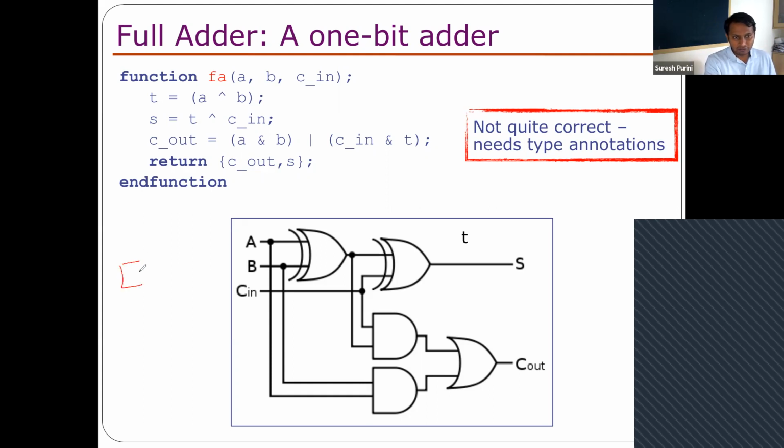If you are designing a 4-bit adder circuit, you have a sequence of 4 full adders, each with 2 input bits, a carry in bit and a carry out bit, with inputs A0, B0, A1, B1, A2, B2, A3, B3.